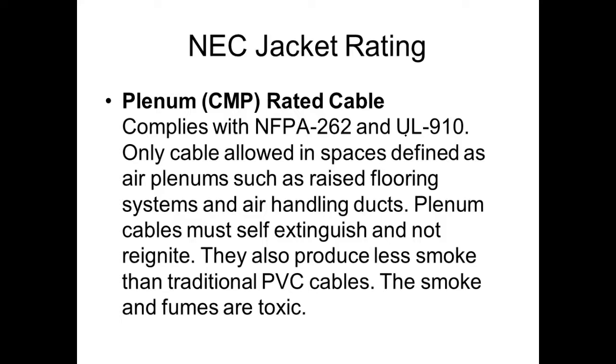The plenum cables must be self-extinguishing and not reignite. They also produce less smoke than traditional PVC cables, and the smoke and fumes are toxic. So if you're going to run cable up in here, or if you're going to run it through that floor plenum, you need to have plenum rated cable, because that's circulating air, right? You understand that? You get all these toxic fumes and that garbage.